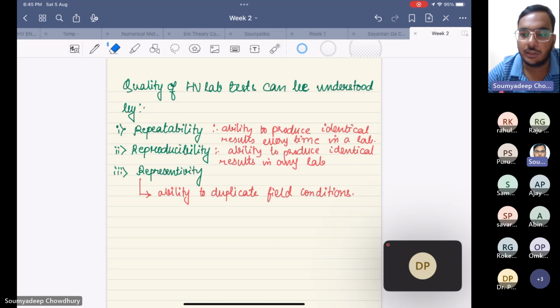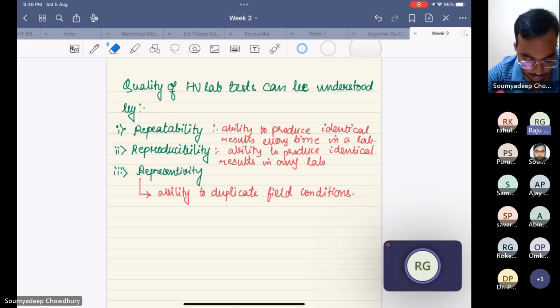But what you are saying is, even if it passes, there will be some deterioration in the quality and performance of the insulator. As per my knowledge, that will not happen; significant deterioration will not happen. No, I am not saying it is the failure. It is just the repeatability, the same test results may not repeat because the insulation has deteriorated. The flashover would not have taken place.